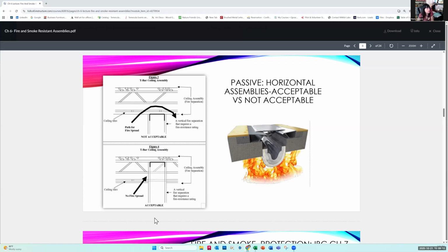Like I was explaining, you need to push that vertical wall all the way to the top of the deck, or underneath the actual flooring of the next floor. It has to be pushed there so it seals this fire path spread and it cannot penetrate through there. You can't have penetrations in here, else it could squeeze through. And this entire element has to be caulked and sealed. So it just closes it off. It's like leaving a gap, and what are you going to do with the gap?